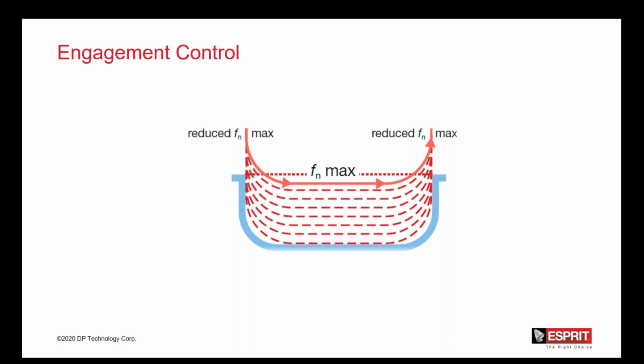All right, so this is talking about the engagement control here, and this has to do a lot with the lead in and lead out, or the roll in and roll out. What this does is it eliminates the negative effects in a traditional plunging, and it's to maintain and reduce the consistent tool engagement. So the profit turning breaks the cutting surface into manageable pieces, and what we recommend is using round inserts to roll in and out of the cut to control that engagement at both tool entry and exit.